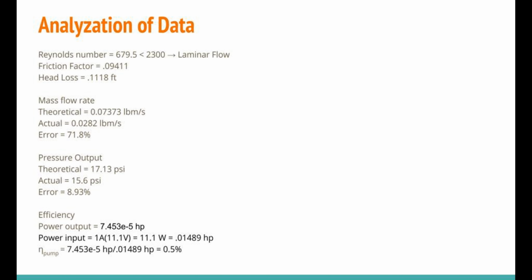As stated before, our Reynolds number was less than 2300, which means it's laminar flow. The friction factor was 0.09411. The head loss was 0.1118 feet. So using this information, we were able to calculate the necessary thermodynamic values that we were trying to obtain in this project.